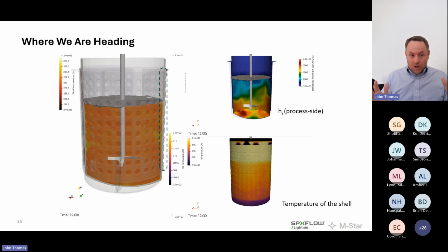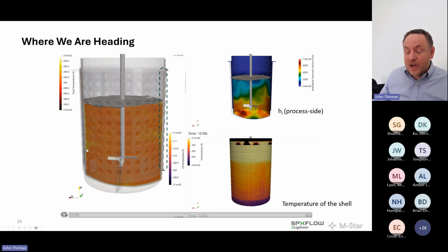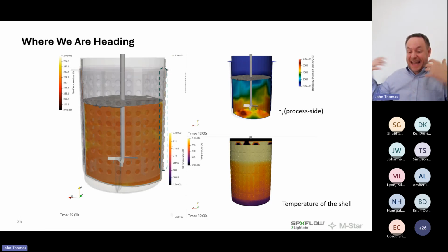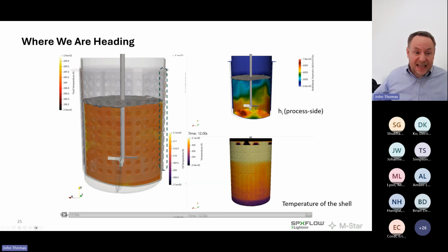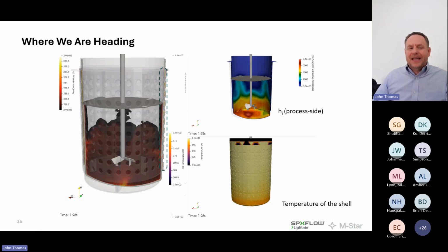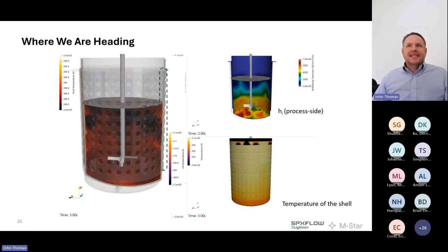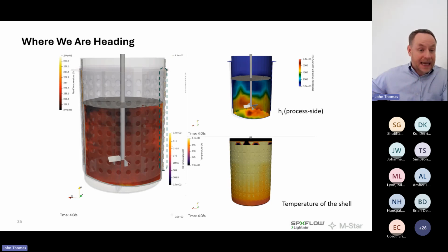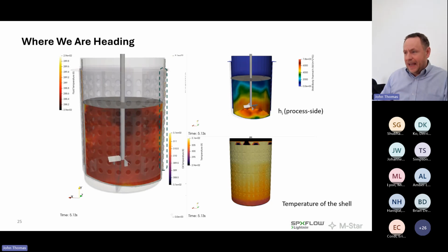That's pretty cool. I want to emphasize we do need to use our semi-empirical boundary layer theory model, which I think I've spoken about at length and ad nauseam. And we do need to specify, again, some sort of wall model, some sort of laminar wall model. Those are easy for the convective heat transfer inside the jacket. So there is some subgrid modeling, and I don't mean to dismiss that, but it's very well validated based on what I've been speaking to at length today.